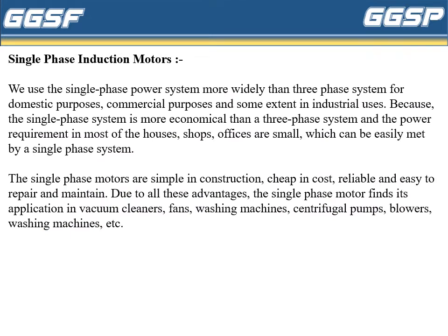Single phase induction motors. We use the single phase power system more widely than the three phase system for domestic purposes, commercial purposes, and to some extent in industrial uses, because the single phase system is more economical than a three phase system, and the power requirement in most of the houses, shops and offices is small, which can be easily met by a single phase system. The single-phase motors are simple in construction, cheap in cost, reliable and easy to repair and maintain.